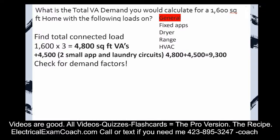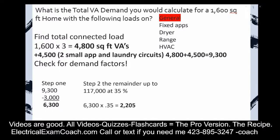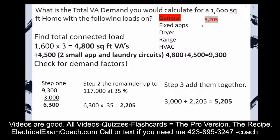Now we check for demand factors. Step one, we're going to take the first 3,000 at 100%. We're going to take that remainder at 35%. Then we take the two and total them back together, and we're going to put that over here on the right-hand side. Every time I want you to write it out just like this, add in each load, total them up, and you'll be on your way to doing the whole house.